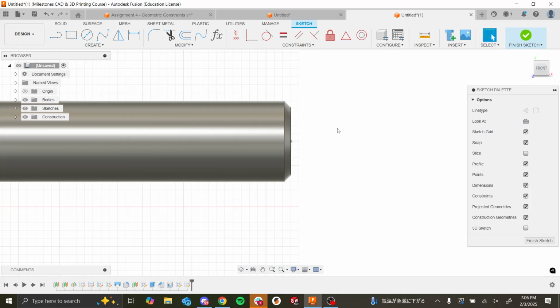If you ever want to reference something that might be like a feature or something from something else, you can use something called projecting a feature. So in this case, I want to make sure that the line that I create is centered on this handle, right? So to do that, I'm going to reference part of the handle and then build my sketch off of that.